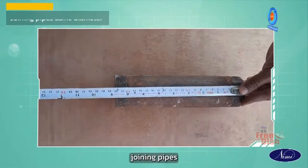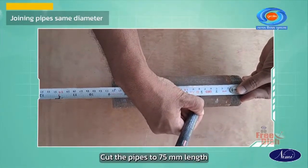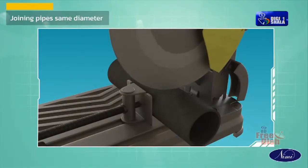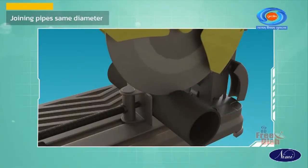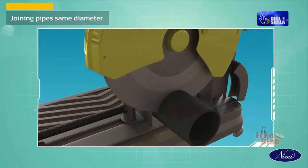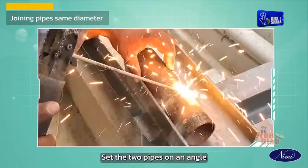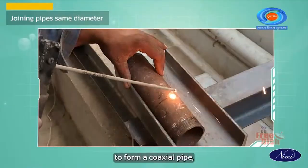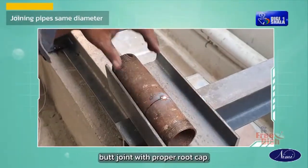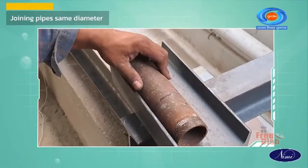Let us first look at joining pipes that have the same diameter. Cut the pipes to 75 mm length using a hacksaw and file its end square. Set the two pipes on an angle or channel fixture to form a coaxial pipe butt joint with proper root gap. Follow necessary safety precautions.